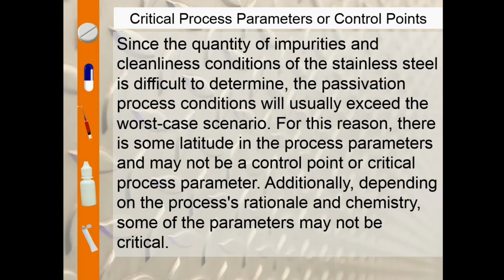Consider a sanitization recirculating a hydrogen peroxide solution. We probably need some milligrams or grams of hydrogen peroxide to kill the few bacteria, depending on the solution's volume, but very likely we will use some kilograms of hydrogen peroxide. We need a 0.5% solution of hydrogen peroxide at 20 degrees Celsius for 1 minute to kill a bacteria. Although our conditions are 3% solution at the same temperature for 30 minutes.